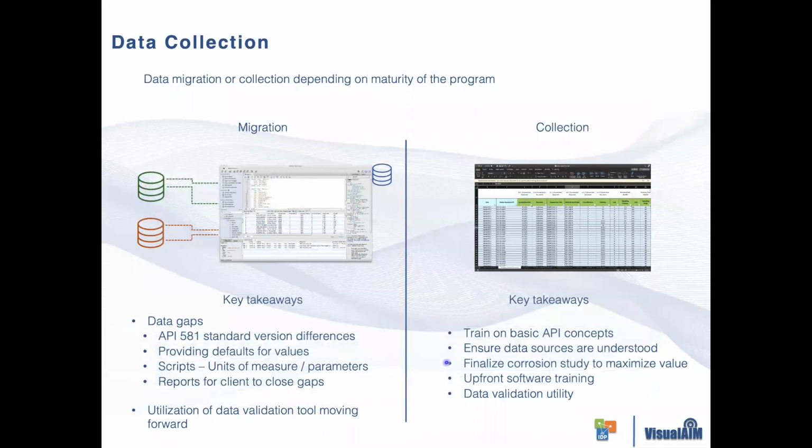With regard to the whole mechanical integrity process, after you've defined the scope of the assets that you're going to perform the RBI study on, you typically also perform a corrosion study to understand two things, basically speaking. One, the different damage mechanisms that will be present in each component, and also the different corrosion rates that would apply to these particular damage mechanisms.